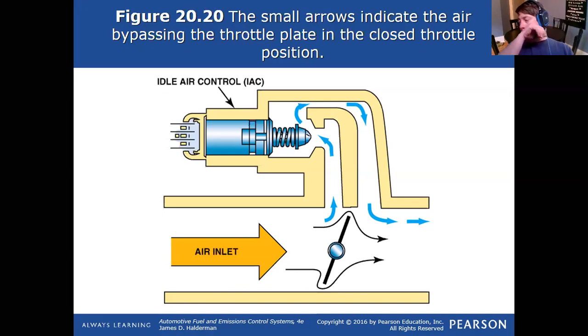And the other side of that is, on a cold engine, allowing that engine to idle up in speed a little bit in order to get everything nice and warm, so our catalytic converter is able to warm up and be efficient, and so our cylinder heads are able to warm up and be efficient. You see this in the morning time. You start your car in the winter and it idles at 1200 RPM instead of 800 RPM. So the component that's actually doing that on your non-electronic throttle plate. That's important.